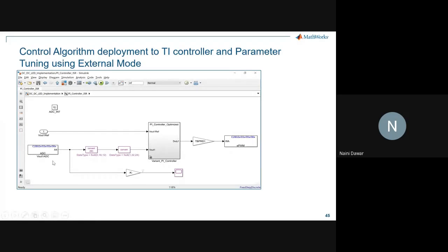If you see this entire system, your application layer and your software layer, which is your device driver, all come into one frame, and with just one click of a button you can take your Simulink model to that particular Texas Instruments hardware board, by mentioning which output or EPWM controller you are using and its configuration parameters.